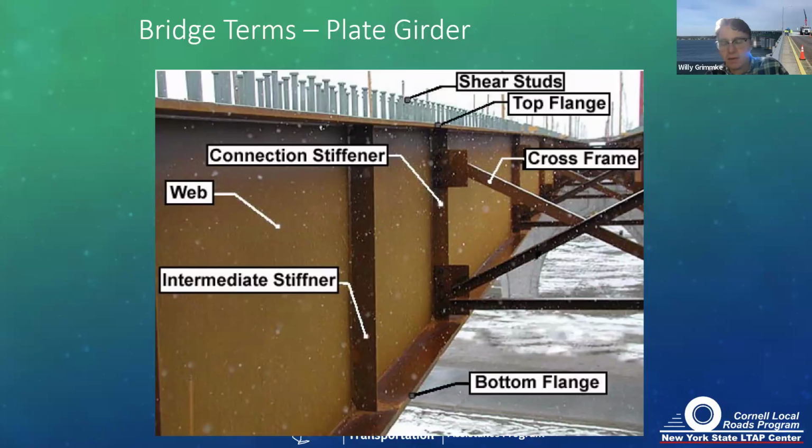And then if it's going to be a concrete deck that's acting in composite with the steel girder, we will have shear studs welded to the top flange to connect everything together once the deck is placed.